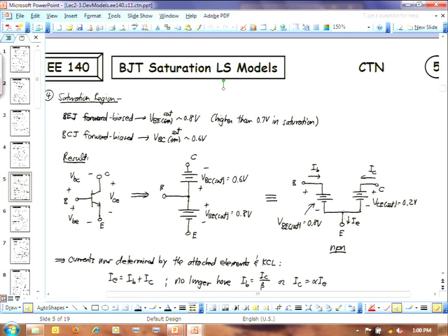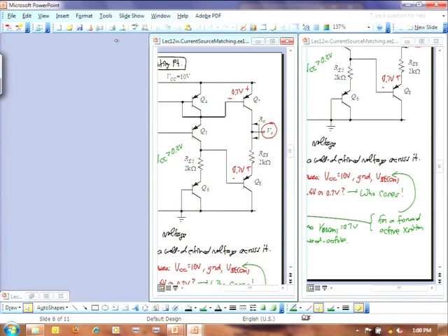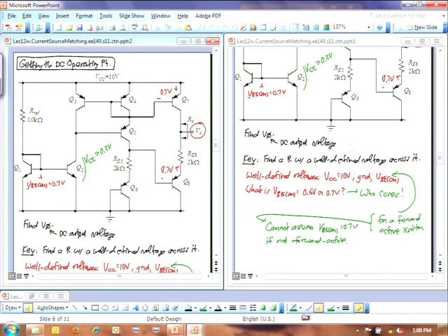And these are all in that first day lecture, or second day lecture. You can go back to that and just refer to it if you want to remind yourself of what these transistors do for DC bias points, if they're forward active or not. But let's just continue with this here. Right? VCE's got to be greater than 0.2 volts for that to be forward active. That's something we'll verify later on. Okay? We can't verify it immediately.